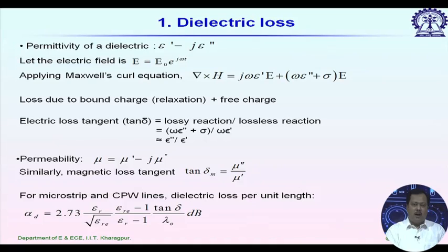Now, we have thermal noise, so due to thermal noise the orientations of these dipoles are in random directions. When an electromagnetic wave propagates through this medium, these dipoles try to orient themselves. In that procedure they absorb some amount of energy, and finally it gives us some heat. So, it is a loss to the propagating electromagnetic wave.